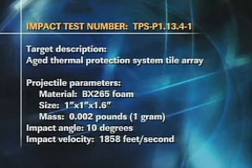And if I can just show you real quickly to give you an idea of scale, this is what a 1 by 1 by 1.6 piece of foam looks like. It's about 0.002 pounds or 1 gram of mass. It's very light. If you hear the term popcorning on the external tank, this is about the size of popcorn that comes off of the external tank, potentially.